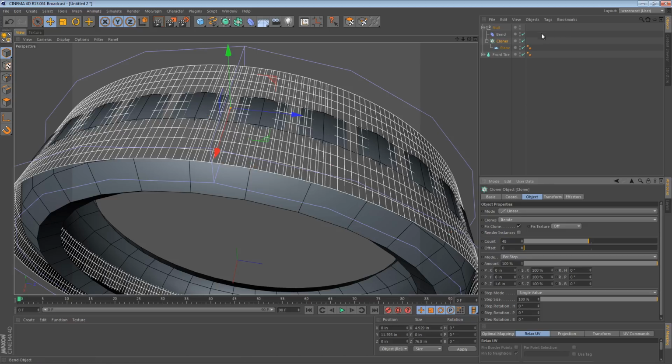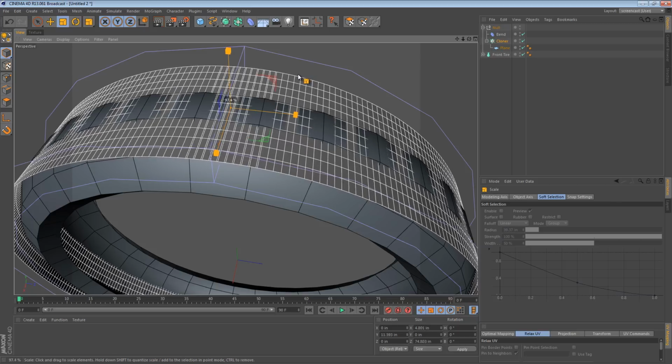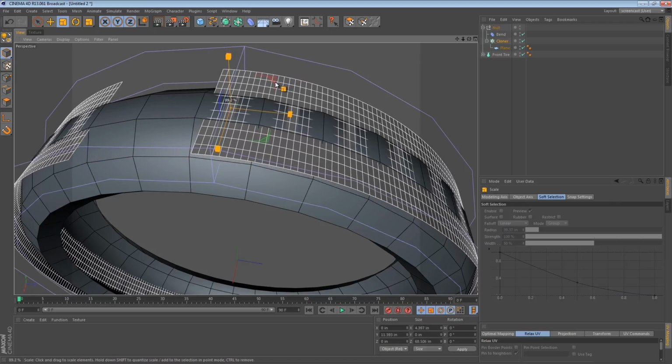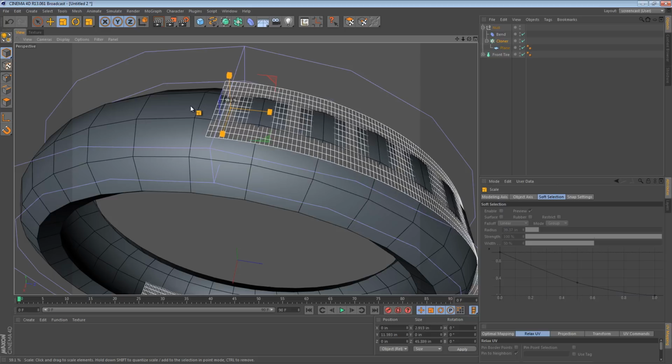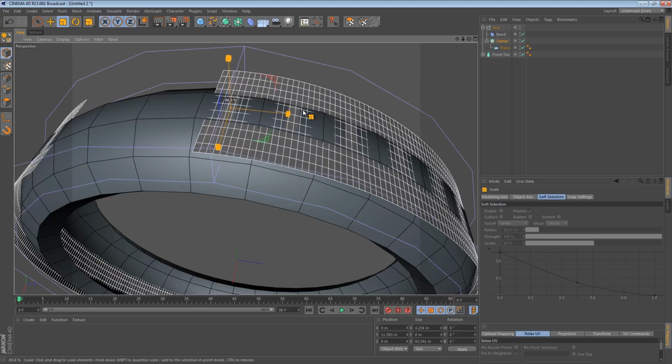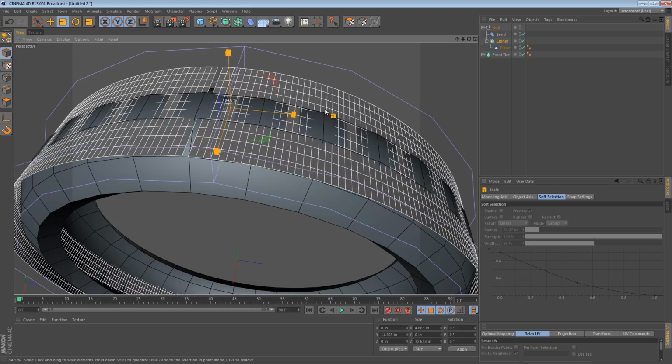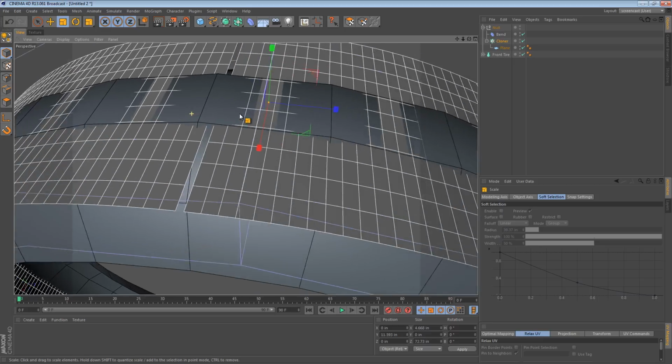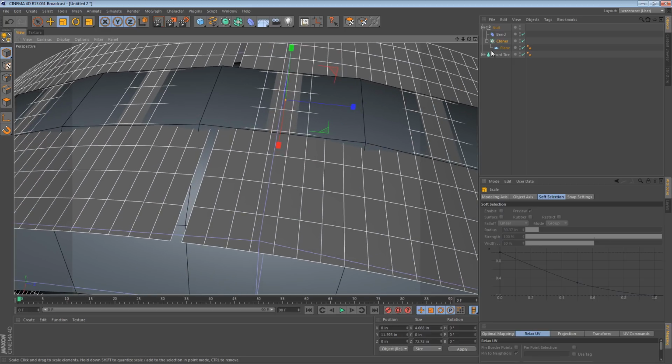But there is a little bit of overlapping happening here. The clones are coming right back around and hitting themselves again. So to fix that, the easiest thing to do is just to grab the cloner, which has an origin of right here, and just scale it. So as we scale it down, we can see that it basically changes the length and the width, but more importantly the length. Now what we're going to do is get it as close as possible, and then go down to the size here and start tweaking the size.